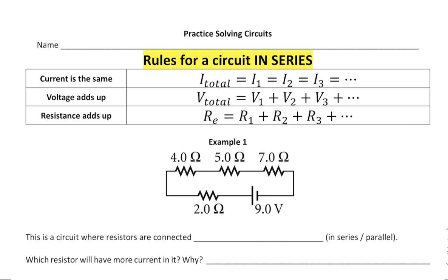First off, how to handle a multimeter that can measure resistance, voltage, and current. There is a certain way that you could put in the prongs and which part of the dial to select in order to obtain the necessary measurements. So in that lab, you looked at how adding light bulbs together creates a lower current. Also, when you played with 1 light bulb, you saw how increasing voltage causes an increased current.